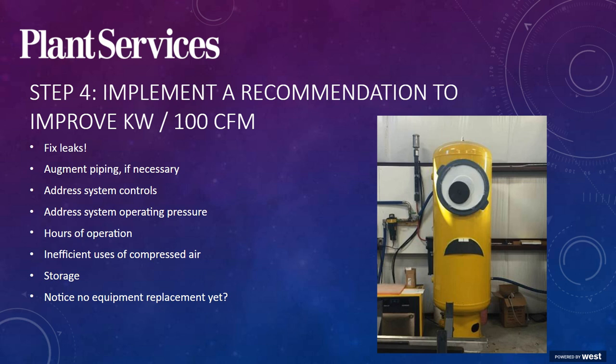All these further points have a small or large impact on station efficiency depending on how your system is operating today. Your compressed air auditor should be well versed in what options should be considered for your system based on the walkthrough, as well as the air audit data they analyze. Notice that to this point, we haven't discussed specifically new compressors. Not to say that they aren't warranted, but in general, focusing on these other items will help assure that when you're ready to replace compressors, you've gotten the most possible savings from your existing system.